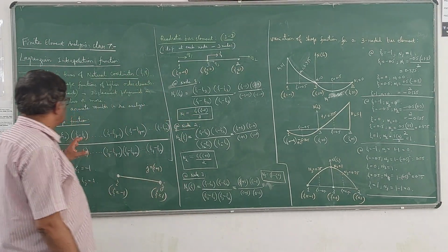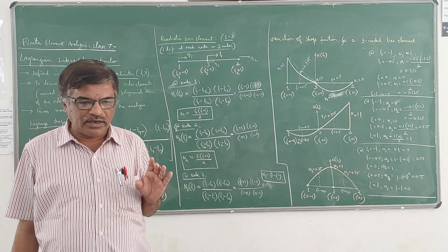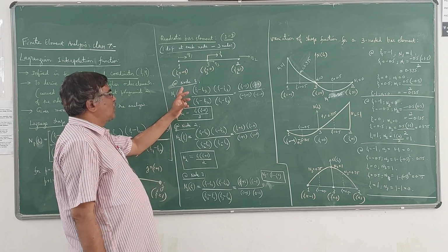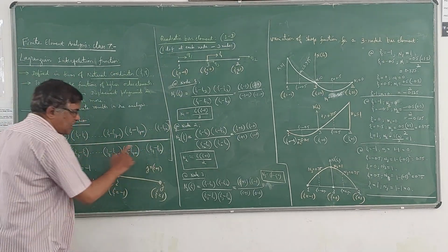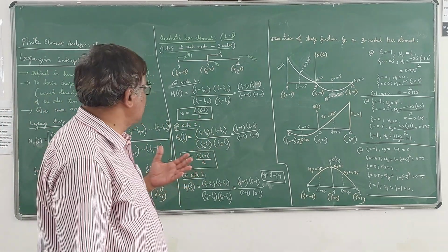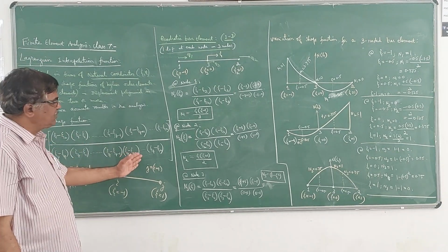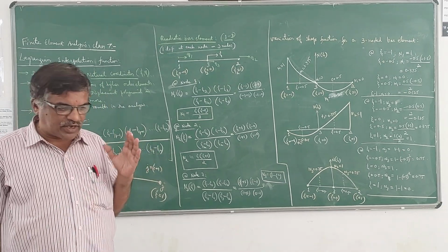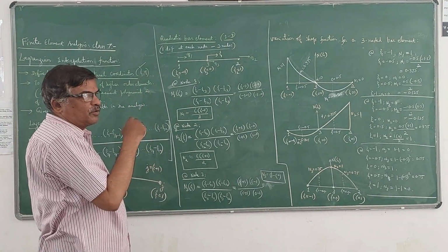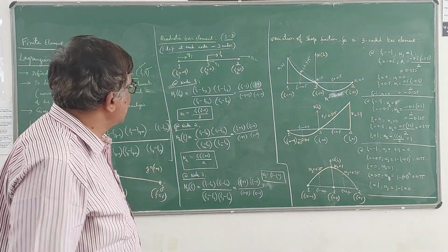Now using this Lagrangian interpolation function, let us find the shape functions N1, N2, N3. For each node, we will have one shape function. All of you observe, this is very important. If you understand this element, you can derive the shape function for any other type of element using this Lagrangian interpolation function, which is defined in terms of zeta. Of course, here it is a one-dimensional element, that is why I am going to use only the zeta term. If you take a two-dimensional element, then the eta term also will come into the picture, which I am going to explain later on.